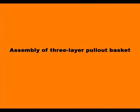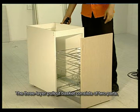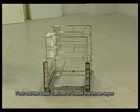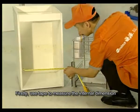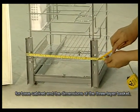Assembly of 3-layer pull-out basket. The 3-layer pull-out basket consists of 2 parts, including the slides and the basket. Find the base cabinet to install the 3-layer basket according to the drawing. Firstly, use tape to measure the internal dimension of the base cabinet and the dimensions of the 3-layer basket.